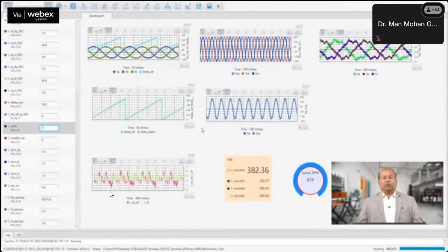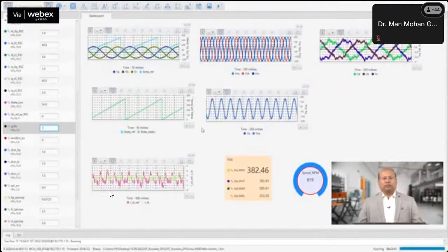By ensuring voltage is less, the contactor connecting the stator and the grid connection is closed, and then the synchronization is done by enabling sync done in the software simultaneously.